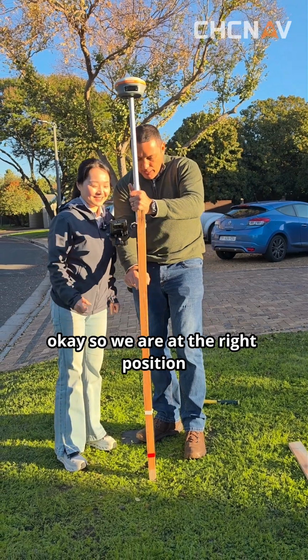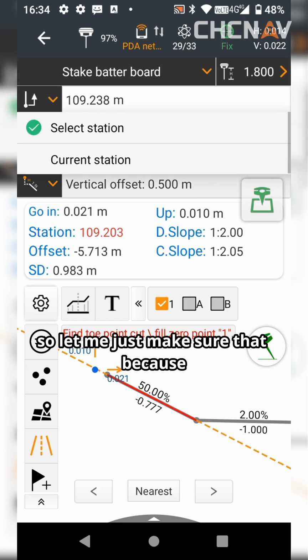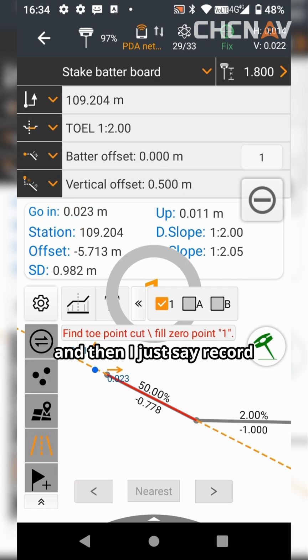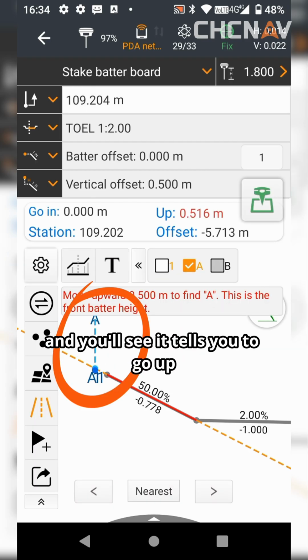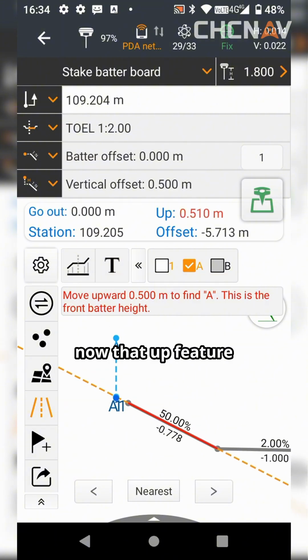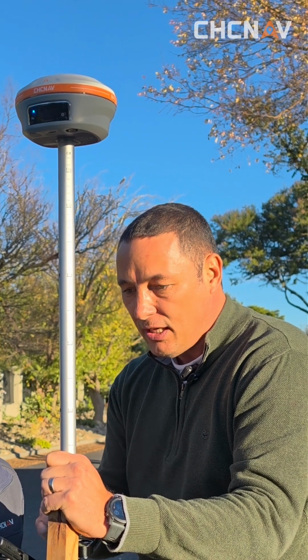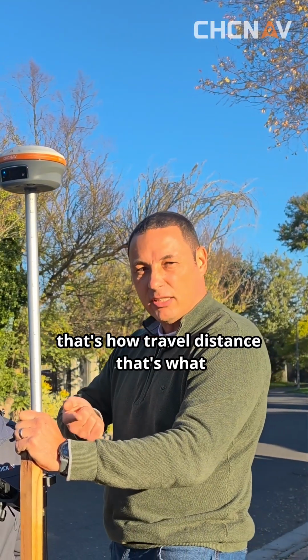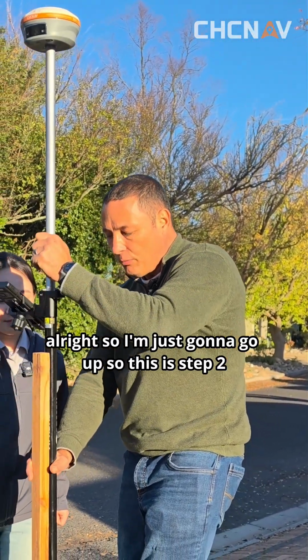Okay, so we are at the right position, and what we normally do is we record this position. So let me just make sure that, because the station changed a little bit, I just say current station again, and then I just say record. Yes, measure. Now the program automatically takes us to the next step, and you'll see it tells you to go up. Now that up feature is because of the vertical offset, which is currently set at 500 millimeters, which means that's 0.5 meters above the design surface. That's our travel distance. That's what we call it in South Africa. All right. So I'm just going to go up. So this is step 2.